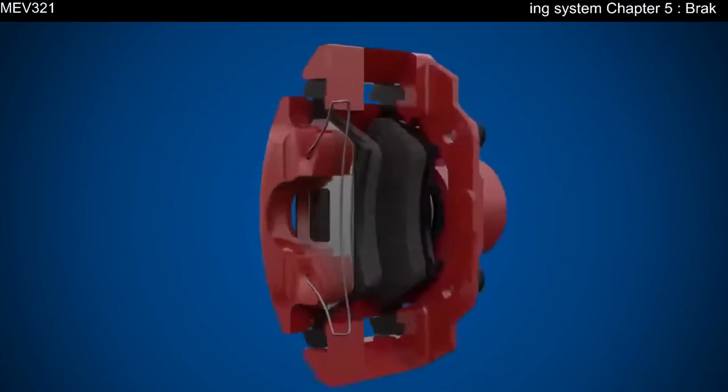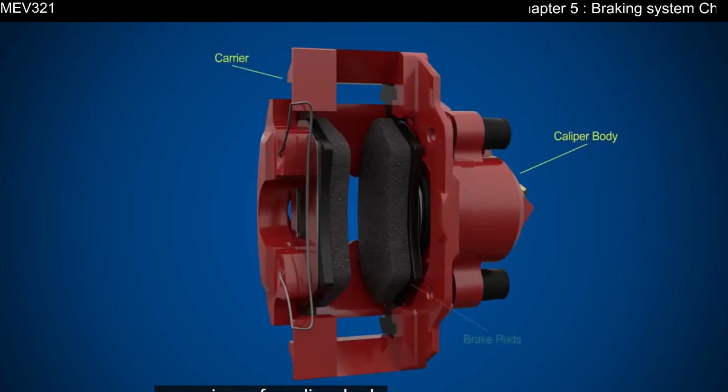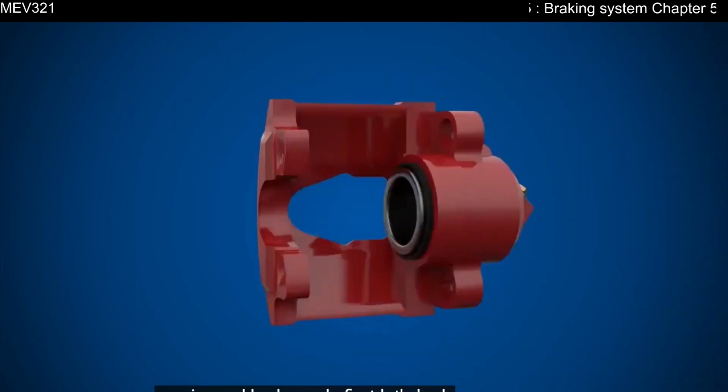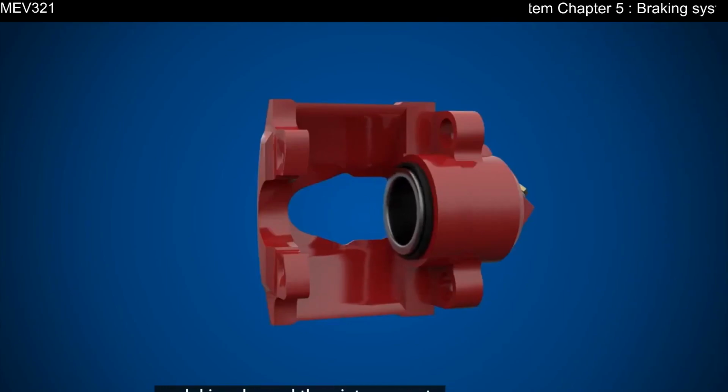The brake caliper assembly provides the mechanism for squeezing the brakes against the brake disc. It typically comprises of a caliper body, carrier, and brake pads. First, let's look at the caliper body. When the brake pedal is pressed, pressurized hydraulic fluid pushes out the piston. When the brake pedal is released, the piston reverts back to its original position. Externally, an outer seal and dust boot protects the piston from dust and contamination.